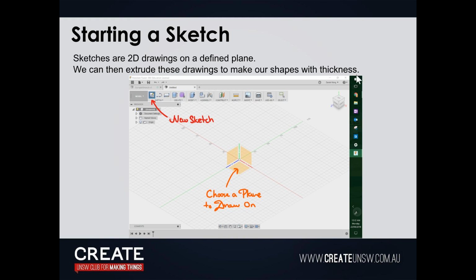So starting the sketch, right? Sketches are 2D drawings. First we'll go into the sketch. We'll just hit create sketch. And now it gives you a selection of planes you want to draw on. I'm already in the top plane, but for example, if we were in this view and I wanted to sketch, it will let me select a plane that I want.